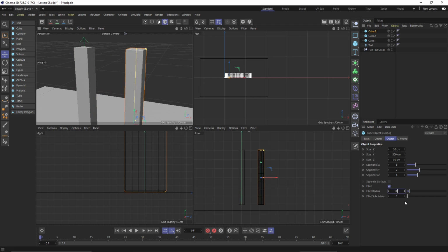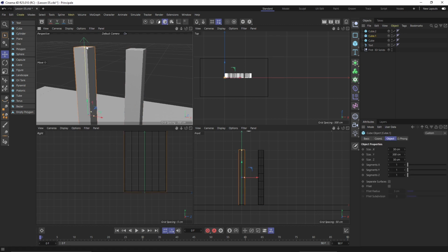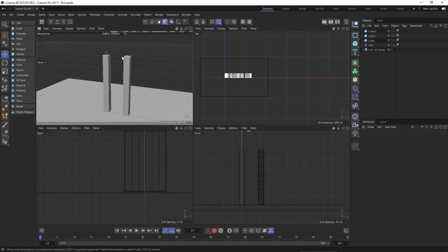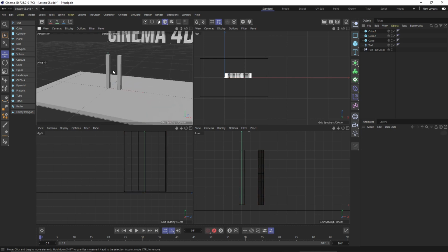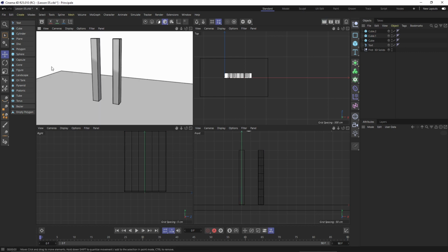Now, in reality, we don't have straight corners. We always have a small fillet somewhere, or a small chamfer. So always make sure that you don't have any straight corners. Just round everything up, and it's gonna look more realistic and nice in the render. You can just run a render right away like this.